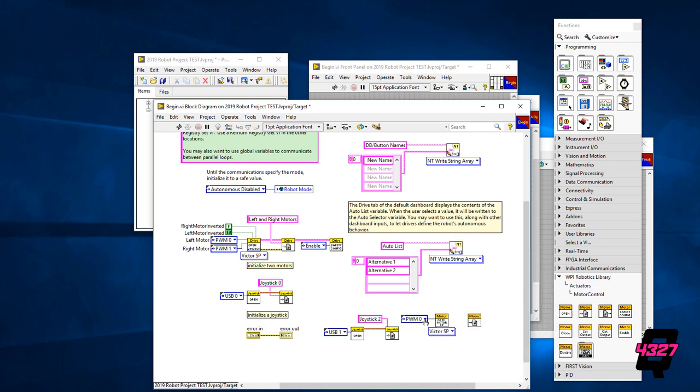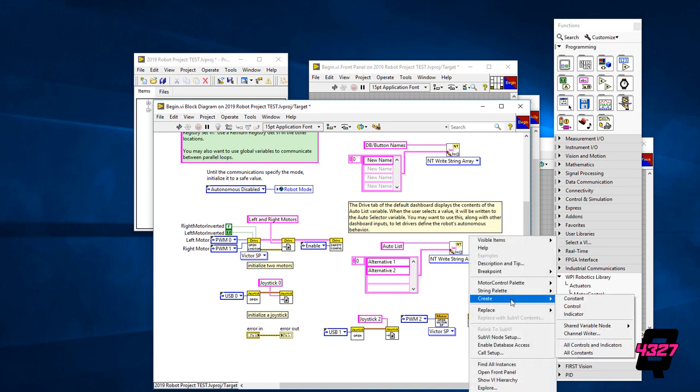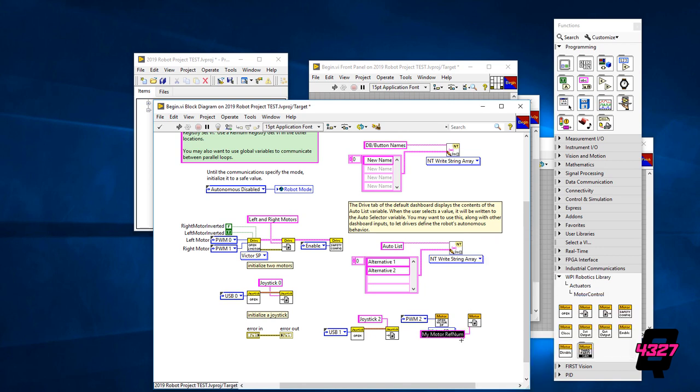Just like the previous video, we will need to tell the computer what we plan to name this motor and where to find the information. Start by moving your mouse over the open icon and right-click on the blue dot to create a constant in the blue box. Unlike the joysticks, now your computer is going to ask for what PWM slot to send information. These are on your RoboRio, and the drive motors likely already took up slots 0 and 1. So let's make this one PWM2.